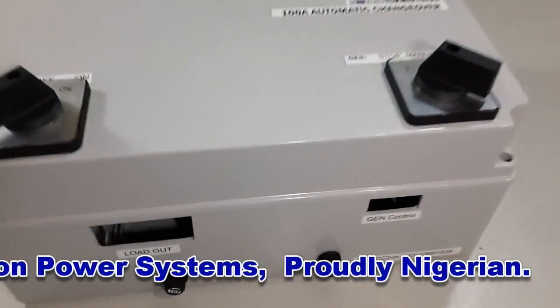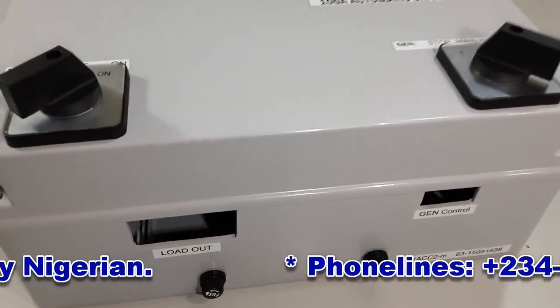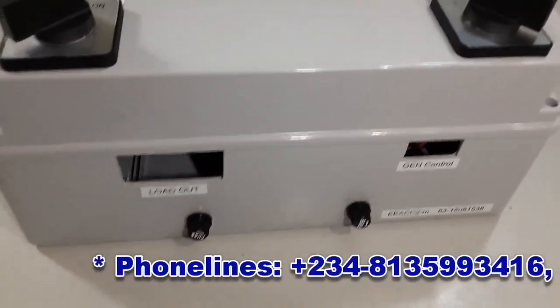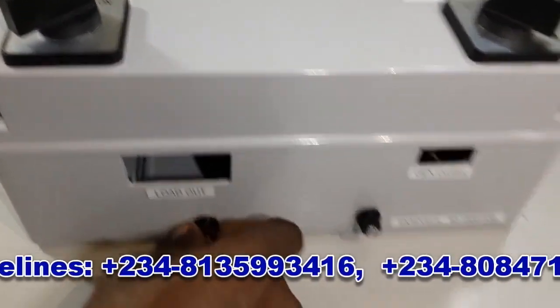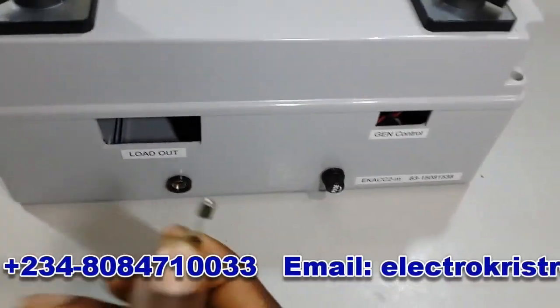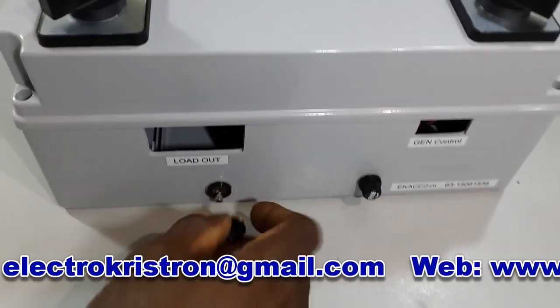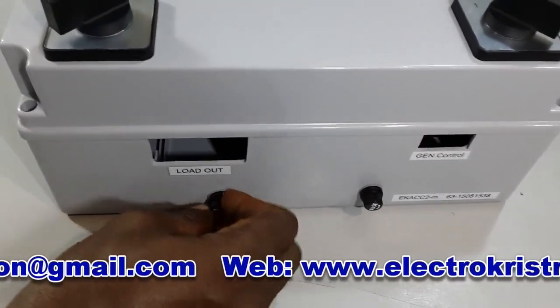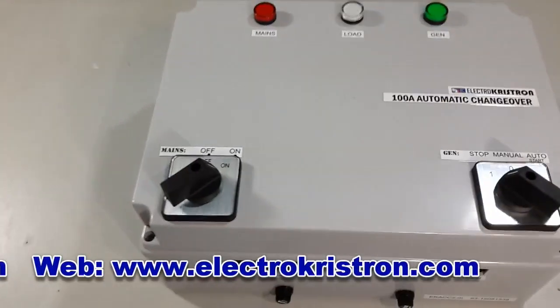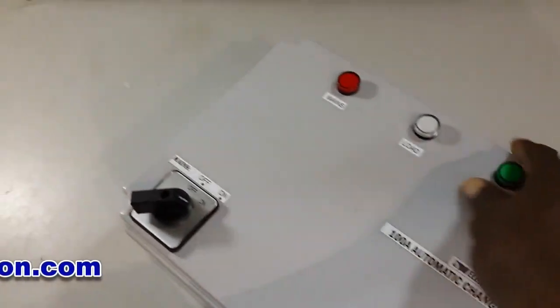The miniature fuses are easy to come by, and in case there is an issue with the system, you can easily open the fuse points to check what the problem might be, if the fuse is faulty or something. Now, if your fuse is not broken, your automatic changeover should function without any problem.